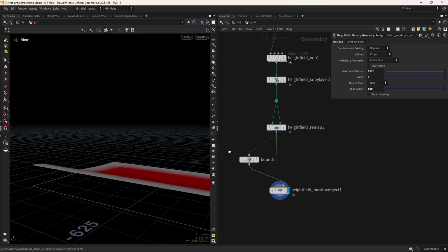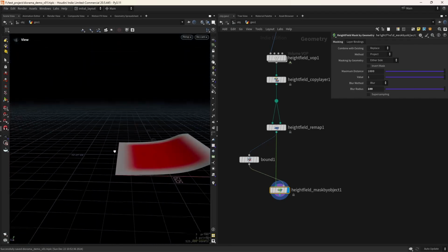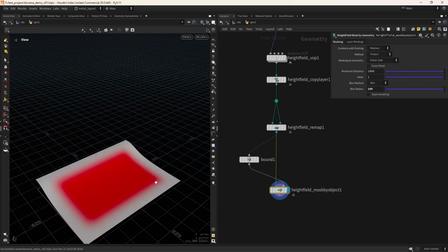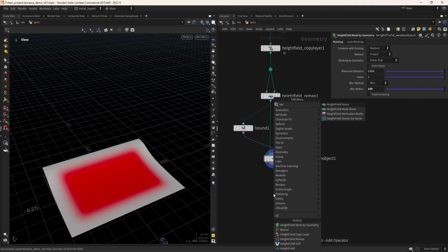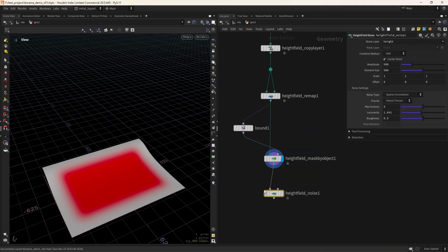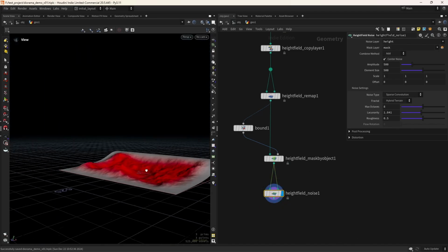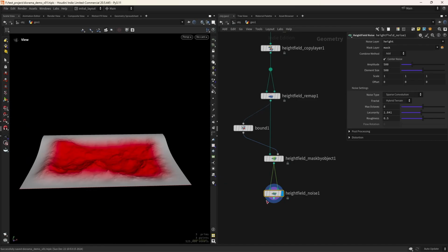And the first idea that I have in mind is to create some displacement near the ground. So some overall noise in the height field. And for that, I'm gonna use the Worley cellular F2-F1 noise. So I'm gonna create a heightfield noise. And then we're going to distort it. So I'm gonna connect the mask. This way we don't affect those areas. So that's a nice trick.